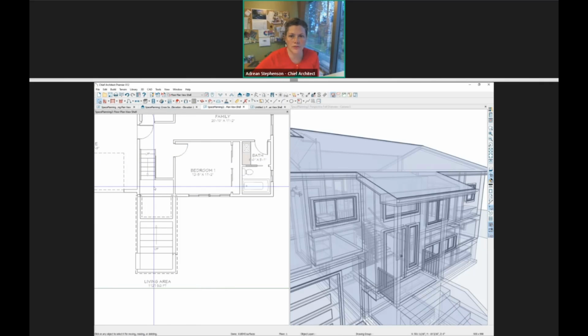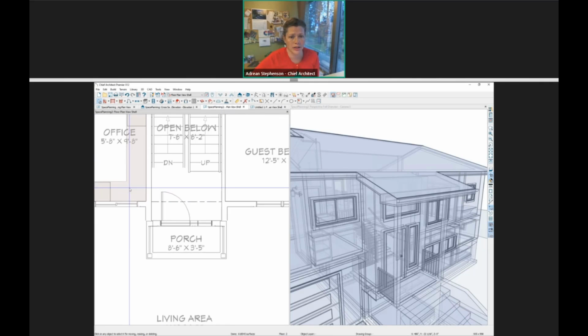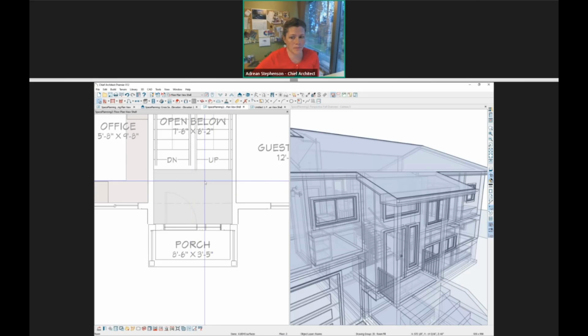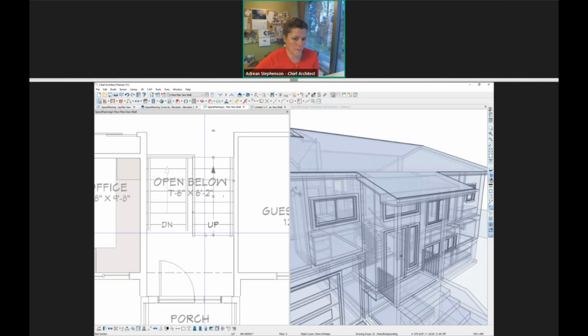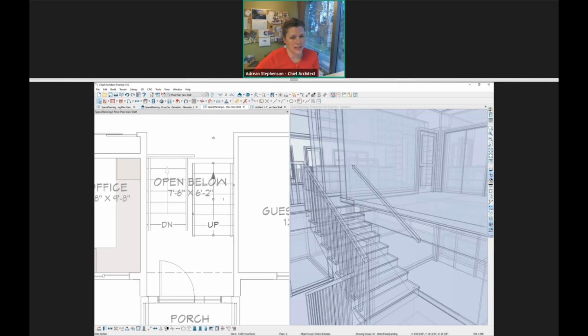So you have your first level, and then on the second floor, you'll need to make sure that you have a good room definition. Then your stair needs to overlap where that wall starts. And when you drag it up to the next step in your platform, the stair needs to actually hit that platform as well. That's kind of the key. If I have my stair dragged back a little too far, it's not automatically snapping up to that level. So that may be what you're seeing.